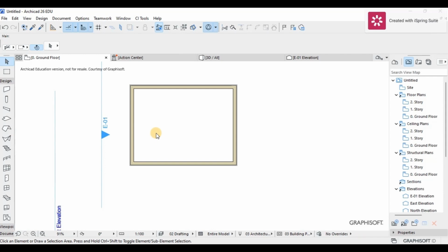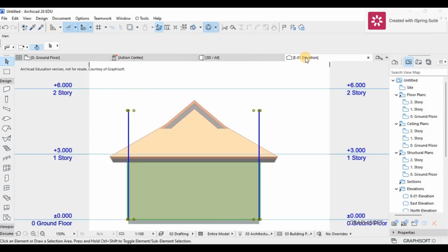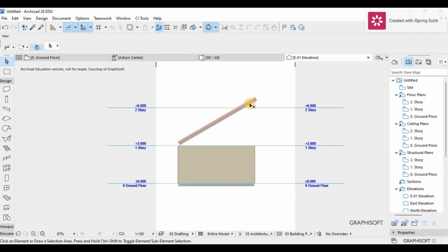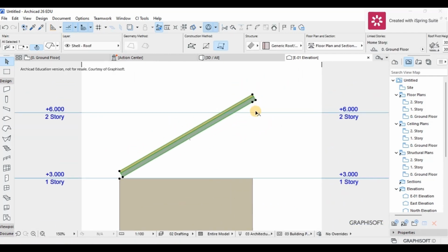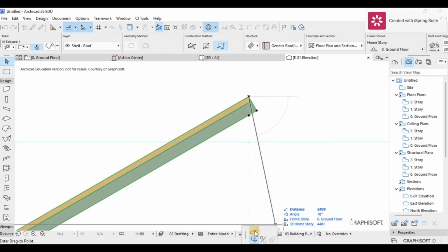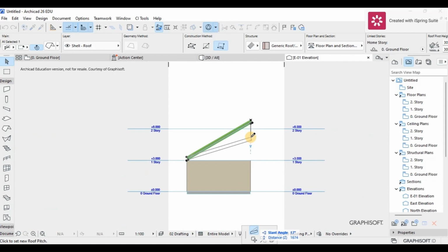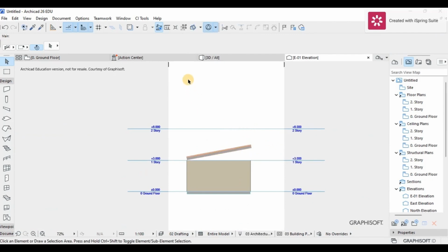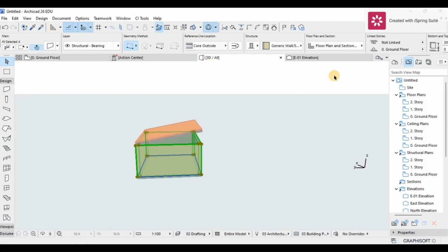And now open an elevation to adjust. Open this elevation again. I think it's already open. And I'm just going to adjust the angle of how it's slanting by selecting the top node here. And then I'm going to select the first option, which allows me to manipulate how it's sloping up to somewhere there. And now I can just go back to my 3D, make my walls tall again, like 5 meters.